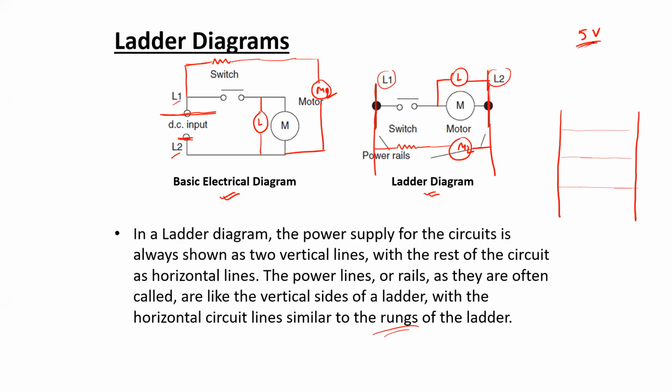The CPU is isolated from the input side and also from the output side using optocouplers. So a common 5 volt source can be considered for the CPU.